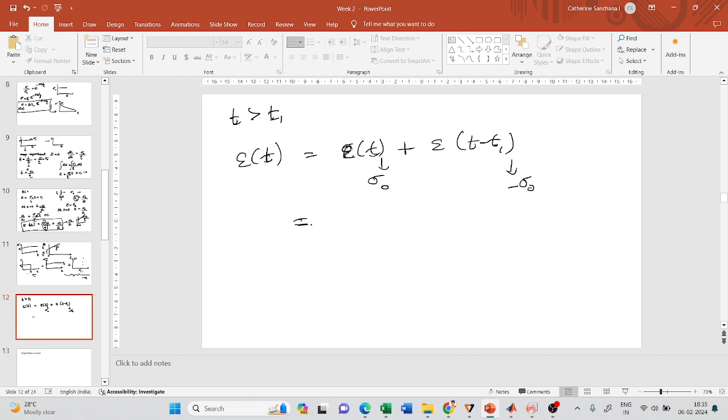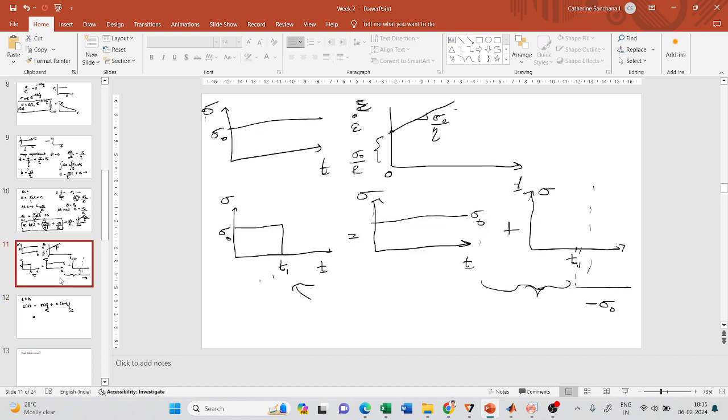So why am I saying this? If you see, this is for the first term. I need the response at time t, and I have to find out the strain value as per this equation, when subjecting the material to a stress of sigma dot. Now, this plus I have to add the response due to this stress also. Only then I will get the response due to this recovery part.